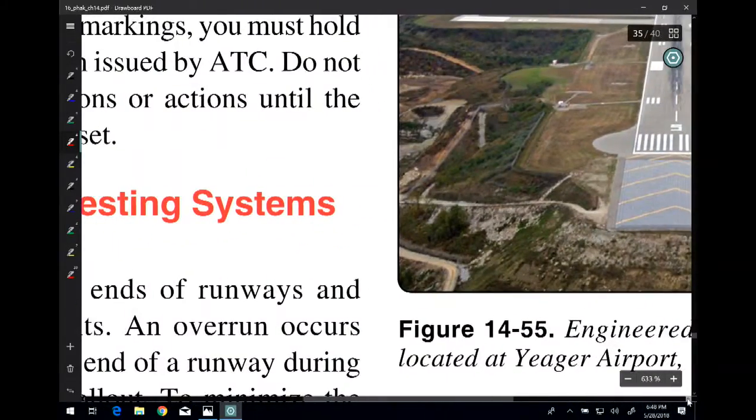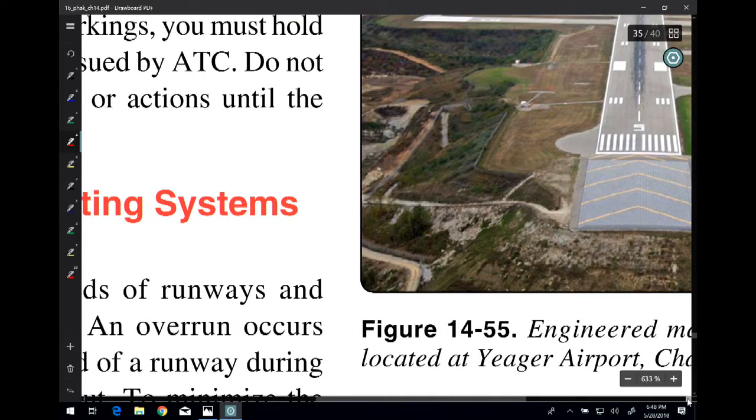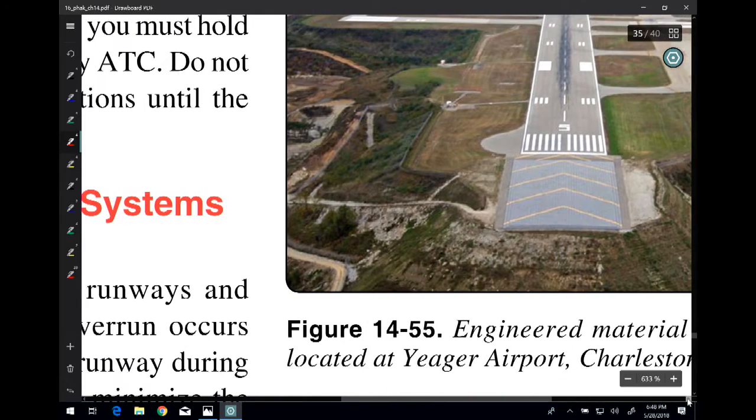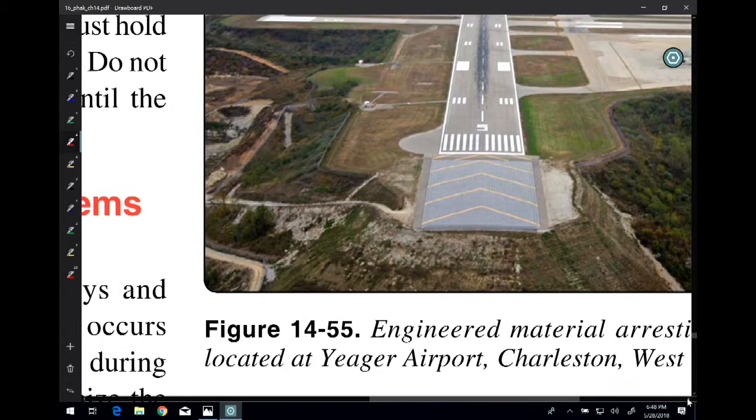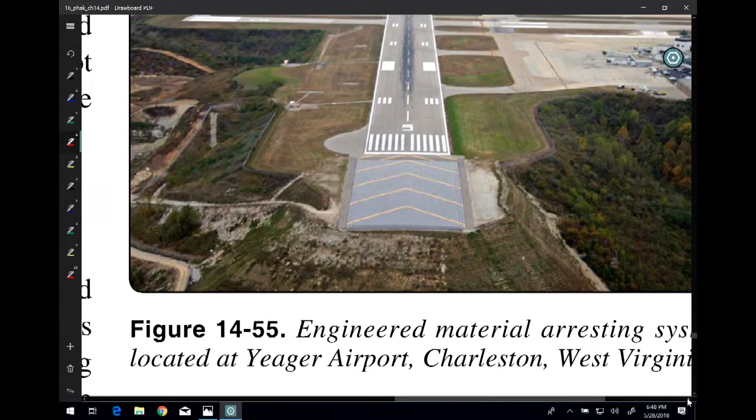And I'm going to go back over here to this image. When we taxi, when we take off, we must consider it a source of immeasurable pride, not to mention safety, to keep our airplane lined up in the center of this runway. Why do we do that? Why do we do it on the centers of the taxiways? Because in some cases our wingspan may be such that we have problems to the sides, and we want to make sure that we keep our airplane in the center.